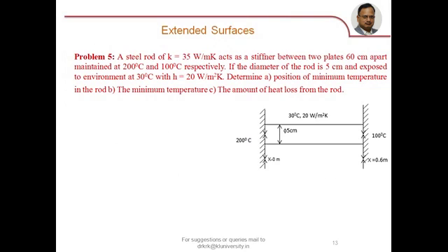Another important application of fins is these stiffener rods. Whenever we insert a rod as a stiffener between two plates, the rod will start acting as a fin, extracting heat by conduction from the end faces and delivering it into the environment by means of convection. The same problem like fins.